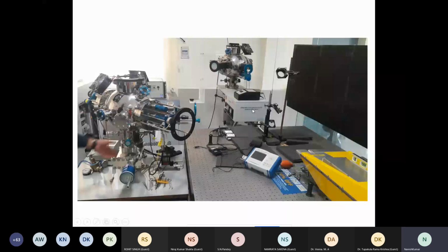One more thing, maybe towards the end I will tell. Once this arrangement of reflection is set up, one should not touch or disturb it. So one has to clamp the whole uprights. Otherwise, if the position of these mirrors is changed a little bit, what will happen? My laser beam will go to some other place, and I will not be able to focus the beam at the target, and I will have to struggle a lot for getting deposition or getting plasma, right?